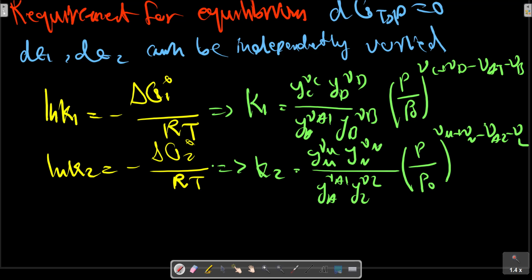A different approach is typically followed in situations including a large number of chemical species. This involves the direct minimization of the system Gibbs function G with respect to variations in all of the species assumed to be present at the equilibrium state.